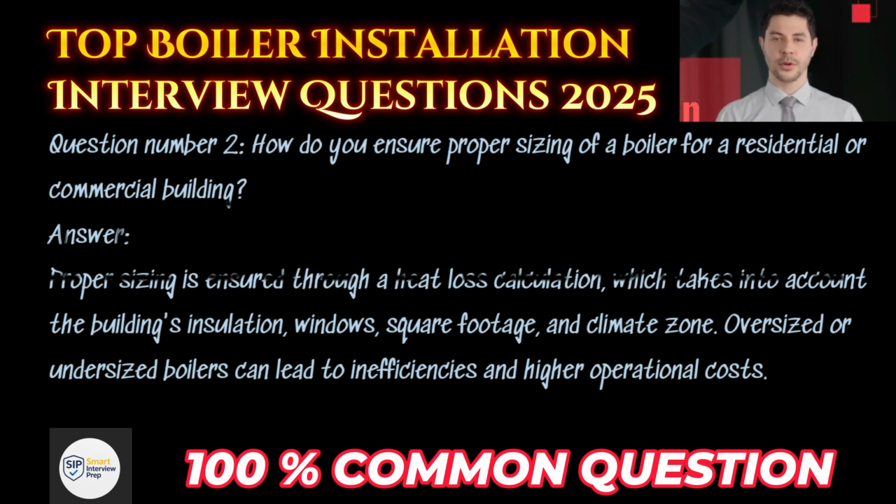Question number 2. How do you ensure proper sizing of a boiler for a residential or commercial building? Answer. Proper sizing is ensured through a heat loss calculation, which takes into account the building's insulation, windows, square footage, and climate zone. Oversized or undersized boilers can lead to inefficiencies and higher operational costs.